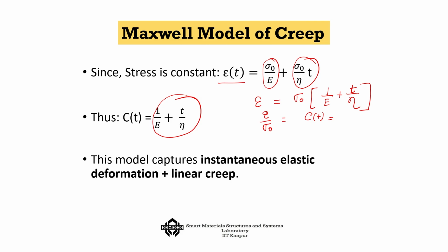So, that means you have an instantaneous term in the creep compliance which you are going to see immediately, and then you have another part which is going to increase with respect to time, and that depends so heavily on the loss factor, because the more the loss factor, the less will be the creep compliance. So, the loss factor plays a very important role in the creep part.